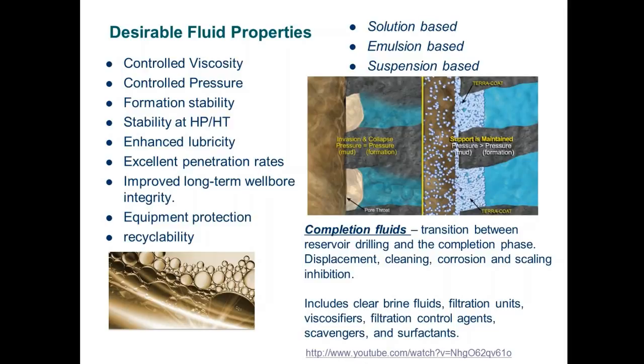So by the way, of course, oil is an emulsion, water in oil emulsion. On the other hand, over time, when you produce more water, it becomes an oil and water emulsion. Erosion, corrosion caused by suspension or different types of particles that are part of the produced oil. It's a big problem not only in the oil and gas industry, but in fact with the geothermal industry. And I've worked with several geothermal companies over the years. They have different sets of problems, but nevertheless, it's all about fluid control and flow assurance.